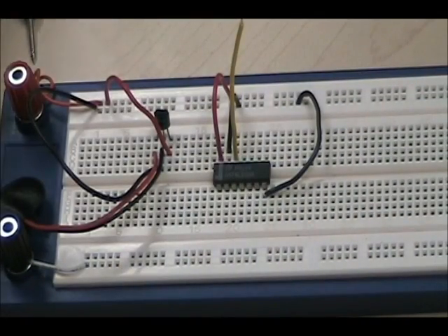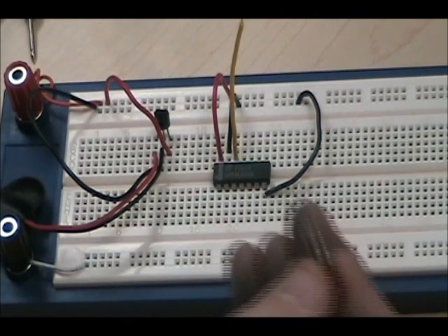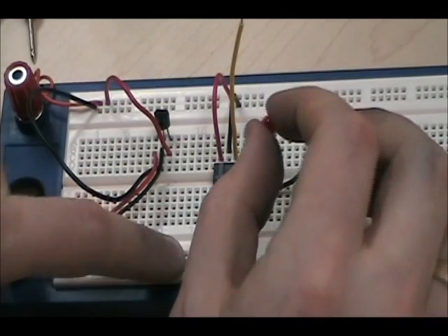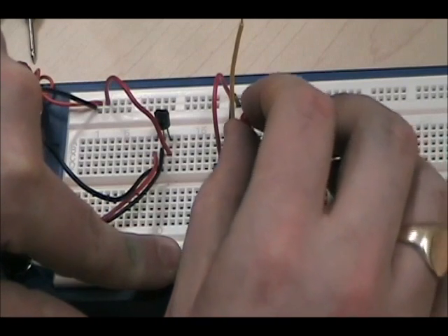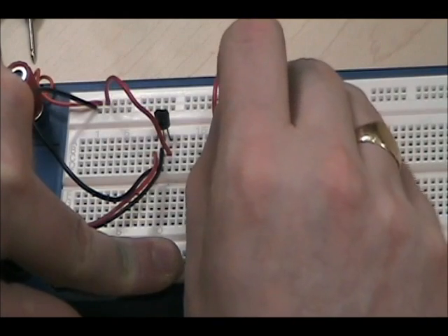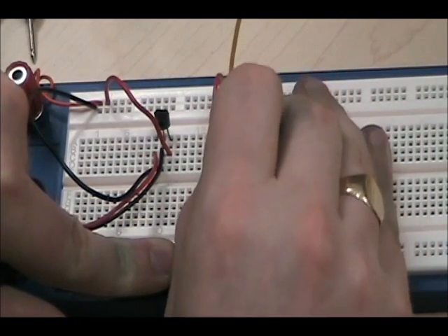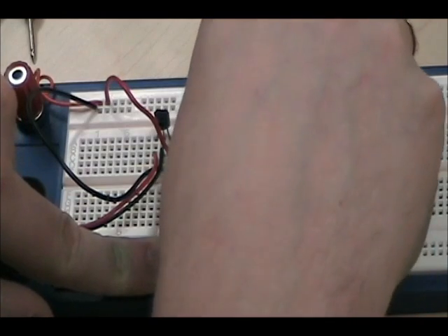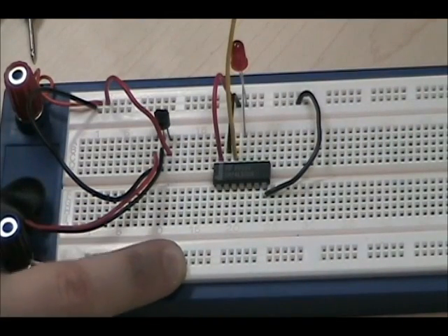We're going to take what's called an LED, a light emitting diode, and I'll tell you more about light emitting diodes a little bit later. Not in this lab, but in another one. Light emitting diodes can only be placed in one way, or else it won't work. It has to be placed with the anode connected to the positive power supply, and the cathode to ground. You won't have to understand this now because we'll talk about it later. The anode goes in the output line, and the cathode, the negative, goes into the ground line.